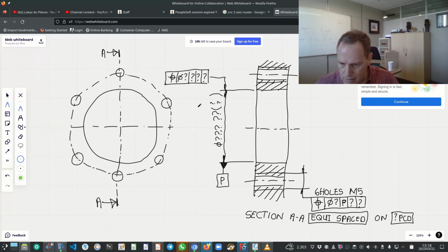So, but anyway, here we need to add the pitch of this 5 millimeter. I think it's 1, but you need to verify that. So 5 by 1 positional diameter, whatever the tolerance is you decide to use. And primary datum P, which is specified here. Secondary datum is either the horizontal or vertical plane, and tertiary datum the same as what we selected here.